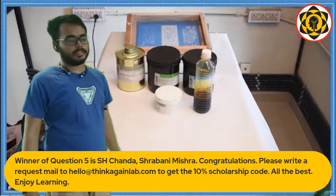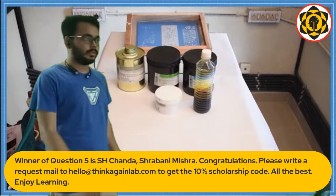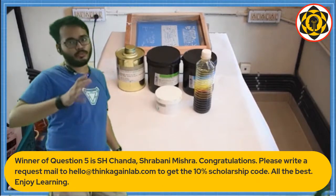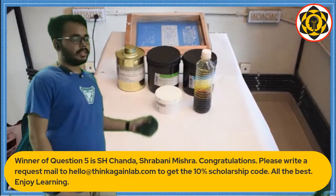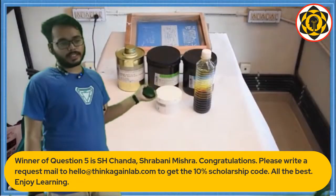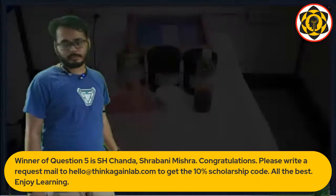And then there is this catalyst. So basically, as I told you guys, you need highly concentrated ferric chloride. Now the concentration that you need is an industrial standard concentration that you won't get in a normal chemist shop. So what you can do is buy a chemist shop level concentrated ferric chloride, and then use a catalyst with this ferric chloride for the reaction to go in the same way.